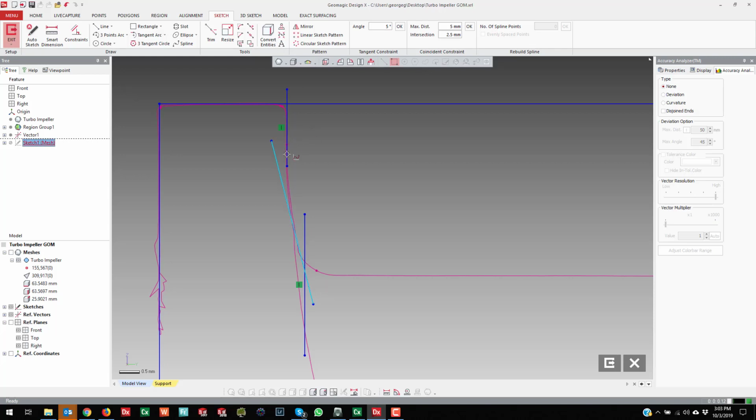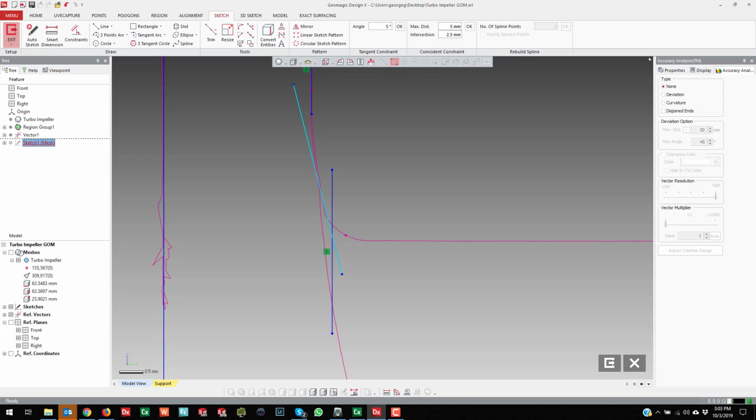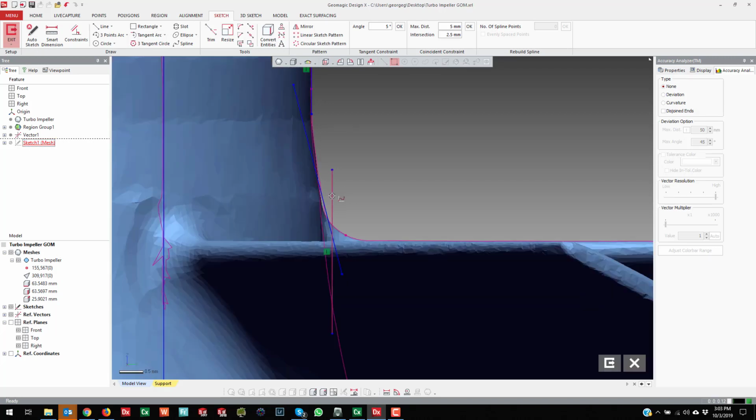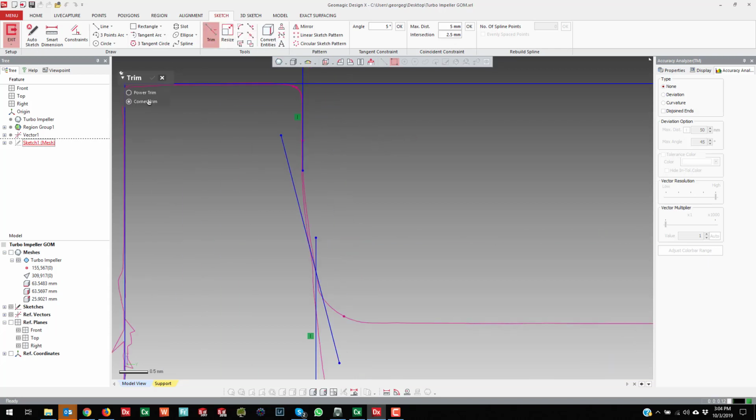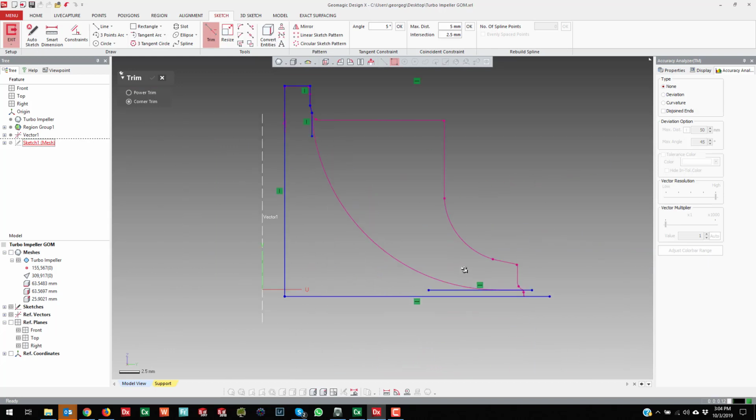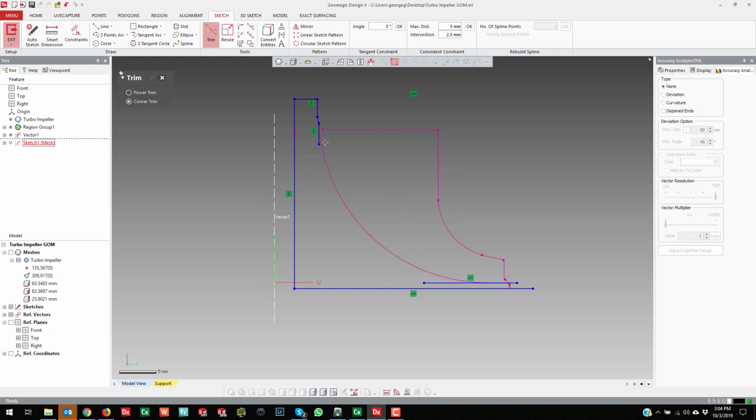And in this, we'll get that into position. And then sometimes it helps to kind of have the scan data; you can turn it on and off and kind of position it from there. So I'll do a corner trim, the second option there. Now, you could do a variety of ways. I could fit a curve here or draw multiple curves. What I think it is, because I've done this before, is a constant radius. So what I'm going to go ahead and do is just trim these two as a corner trim and then do a fillet.